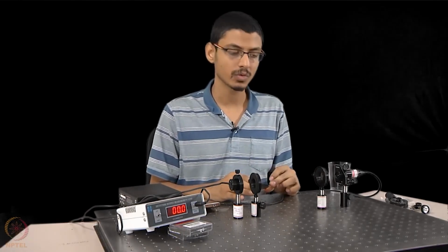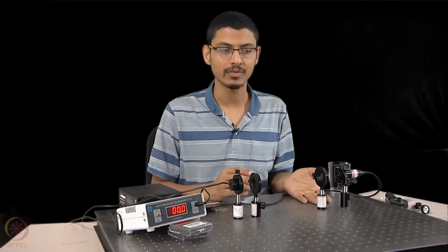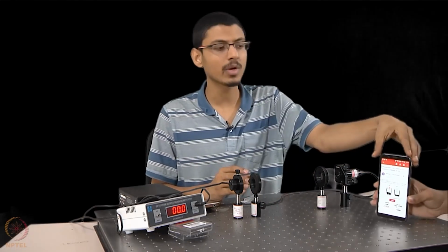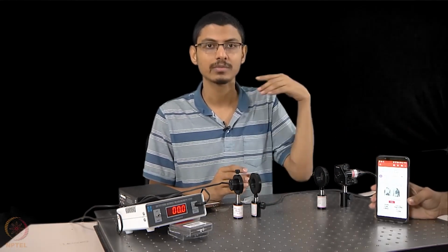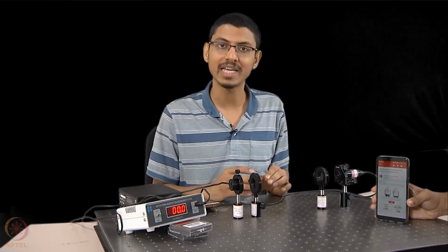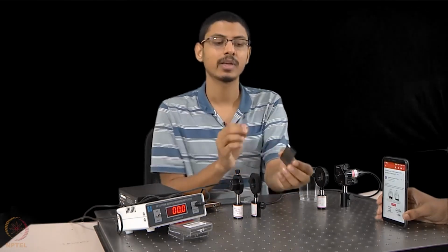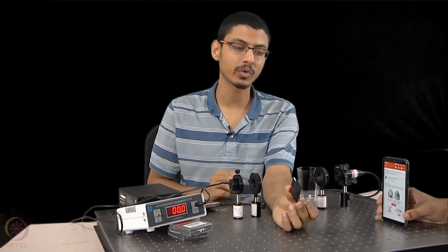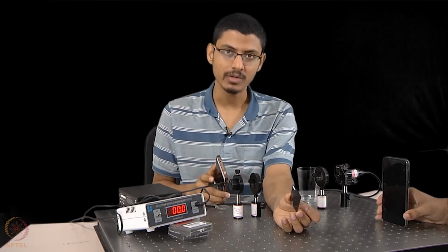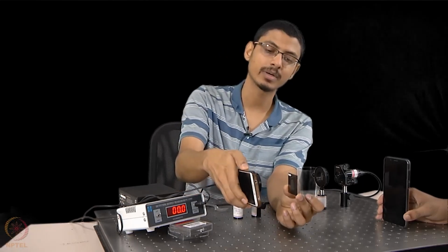One easy way of doing that would be, instead of the laser source, we can use a monitor as a source of linearly polarized light. Or it can be a mobile screen also, if it has an OLED screen. That will also be a source of linearly polarized light. For an analyzer, you can use a polarizing sheet. You can place it at a crossed angle to the polarization of the light coming from the screen. For a pinhole detector, you can use another mobile phone camera to take a picture of the stress pattern. So this is the setup.